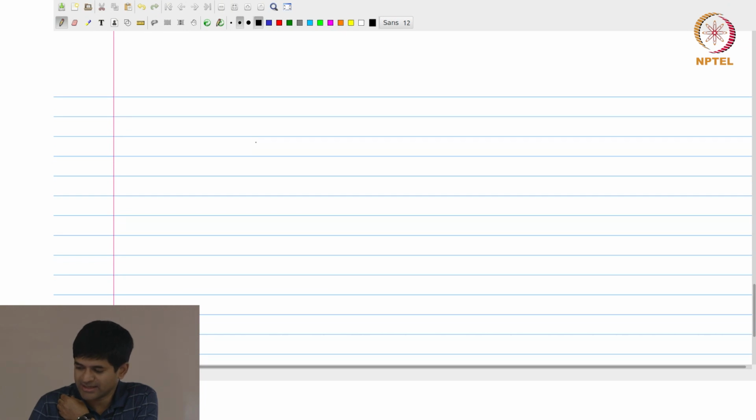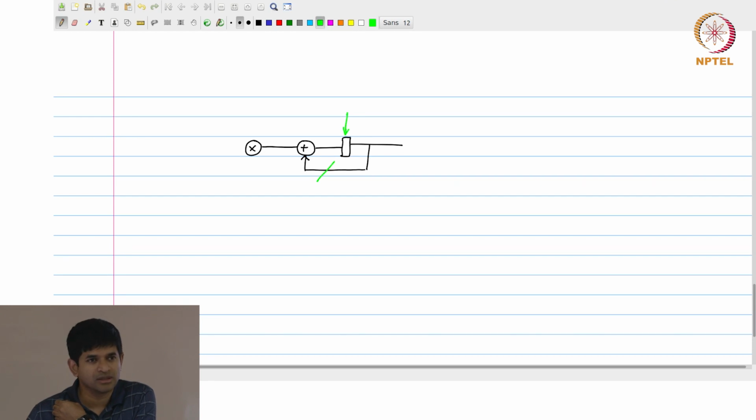What I'm going to assume is that I have one multiplier, the output of that goes to one input of an adder, the output of that adder in turn goes to a register, and the output of this register comes out of the system as well as has a feedback loop going in here. I am going to just draw one green line over here and also one line over here. We'll get to why those are needed later. Those are essentially to be able to reset and break that loop whenever we need it.